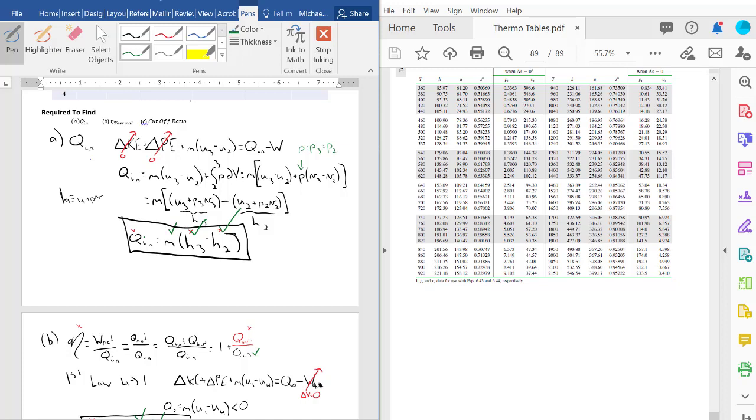So ultimately what we did, right? We looked at the different components of the problem. We solved them all symbolically. And then we went through the effort of fixing all the states. So in a diesel cycle, it's important to know which processes are isentropic, because then you can use the isentropic relationship. Here we talked about variable specific heat, but if we were doing this as constant specific heat, the methodology is essentially the same, just you'll use a different expression when you get to the isentropic relationships, and your delta H's and delta U's will become some kind of specific heat multiplied by delta T.